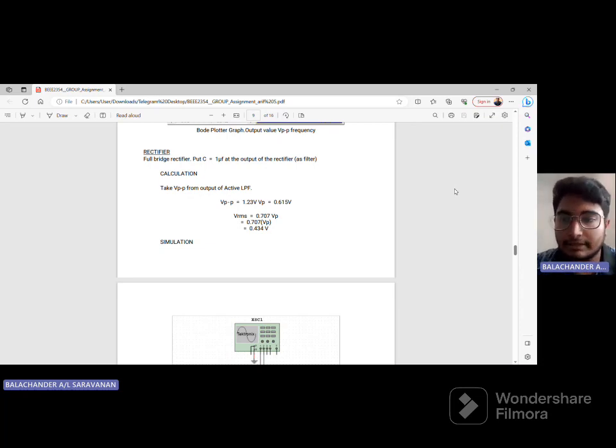My part in this mini project is the rectifier. Today I would like to explain the full bridge rectifier. A rectifier converts an AC signal to DC, and a bridge rectifier does this using a diode bridge. A diode bridge is a system of 4 or more diodes in a bridge circuit configuration.